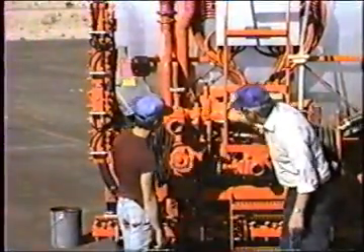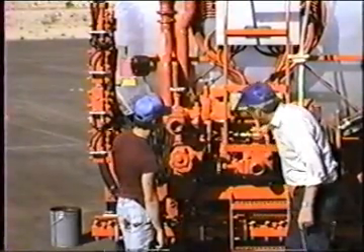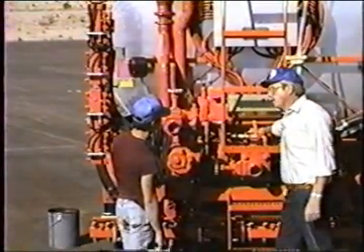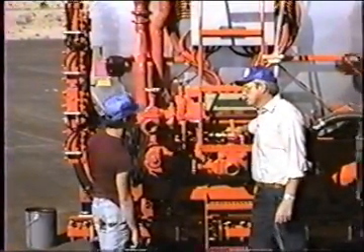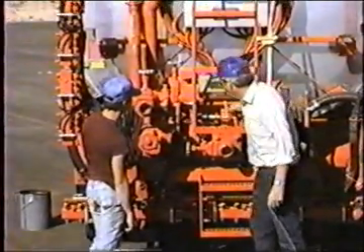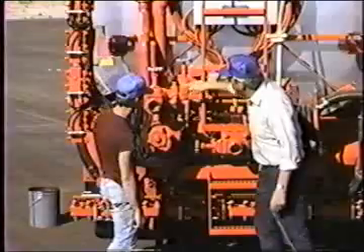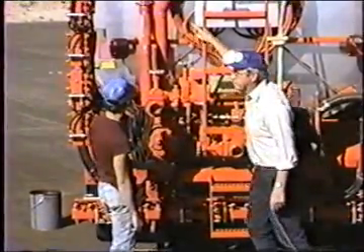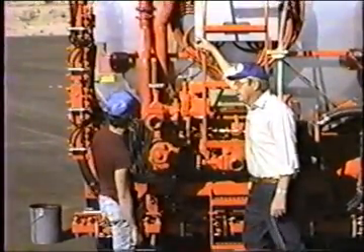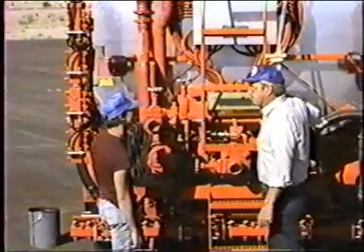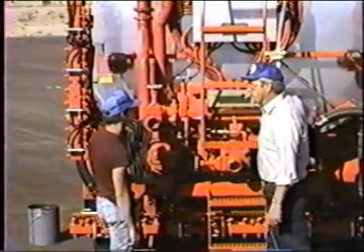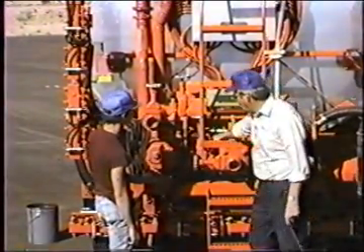We're going into the spray bar valve. We come down to here, and remember, the material is always going to take the path of least resistance. It's going to go the easiest place. Well, if that valve is open, it's going to see an easy route through that valve, right up through that bypass valve, right back into the tank. And it has short-circuited the entire spray bar. Now, there's no circulation going on. It's easy to have that happen.